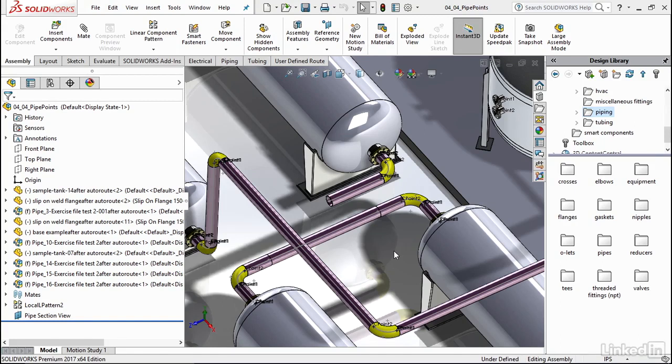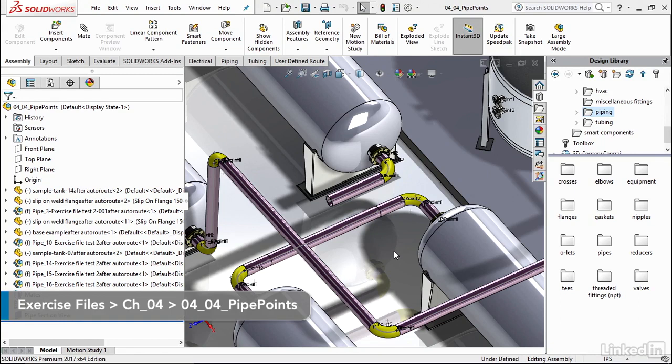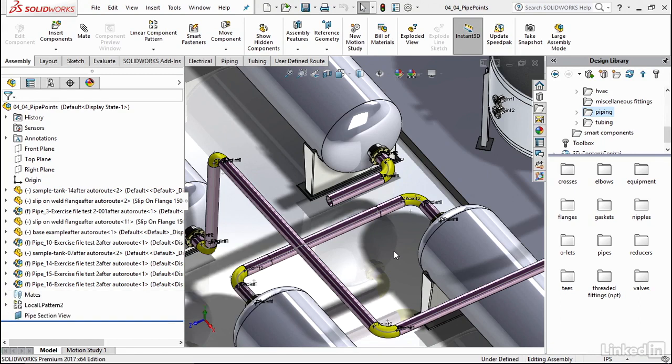If you have decided to weld two sections of your pipe together, instead of using something like a T-fitting, you will need to add penetration points. By creating pipe penetration points, the routing software creates a cut extrude feature and sets offset from surface as the end condition. This will give you more accurate estimates of your pipe lengths needed and show in your model actually what your pipe will look like when it is completed.